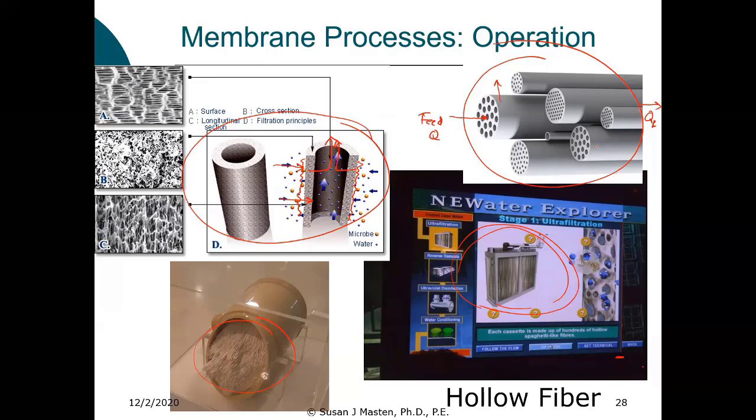But downstream of the donkey paddock, we needed to make sure that we didn't clog the filters because of the turbidity, removed as much of the bacteria and viruses that we could on the ceramic filters, and then also treated with chlorination to ensure that we killed everything else. And we made sure that when we chlorinated, we let that water stand for the requisite 3 hours to try and make sure that we got the CT needed to disinfect.